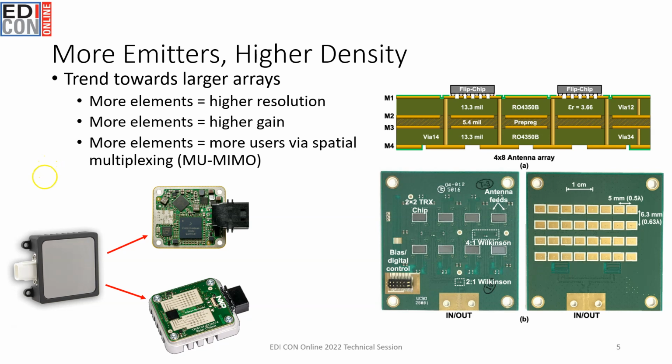And in these 2 systems that I've shown here in this slide, the lower left is your generic radar system. This is actually an NXP design, and I like to show this just because it shows some of the trends in radar. Here in the lower left side on the one layer, you have the radar transceiver connected directly to the antenna array. You've got the transmitting and the receiving array on the opposite sides. You have some dummy antennas here, and you essentially just have 3 and 4 transmit and receive elements.